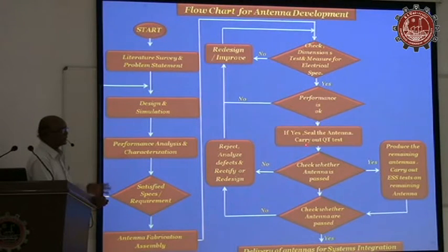If it is airborne, then vibration is very important. Depending on the application, we go for all the qualifications; well-defined procedures or tests are there. We will go for that. Then again check the antenna, whether it is meeting all the requirements or not. If it is meeting okay, then all these antennas we are converting into an antenna array unit for direction finding, where more number of elements are there.